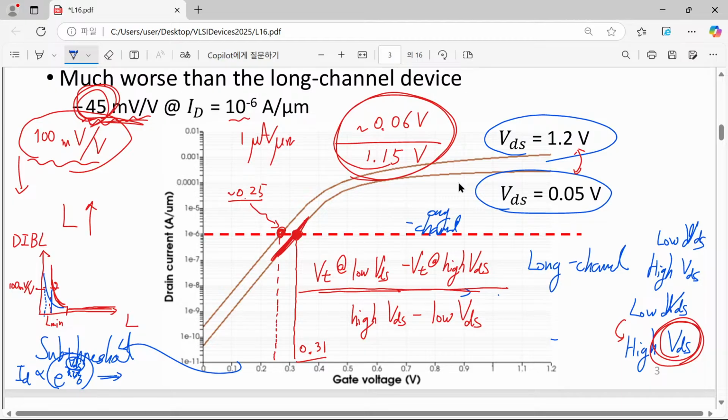Then of course, since your drain current is proportional to the factor width divided by length, if you can achieve an even shorter minimum length scale, then you can increase your drain current. So simply speaking, in order to maximize your on-current, your usual task is to find the minimum length scale which can maximize the on-current.